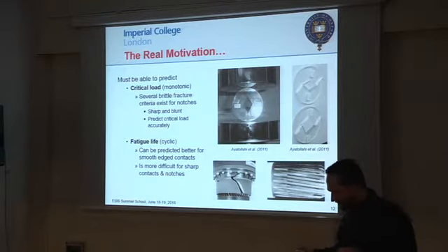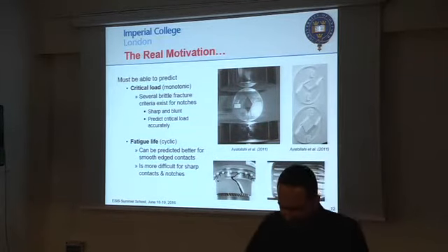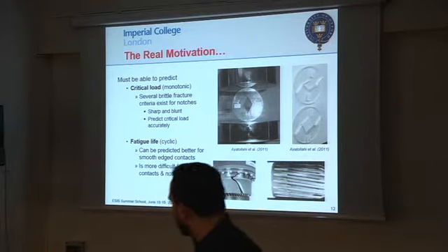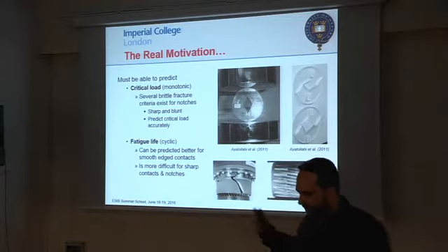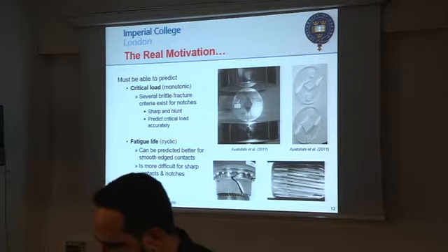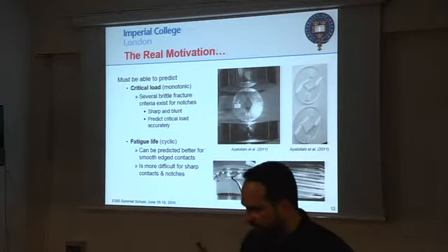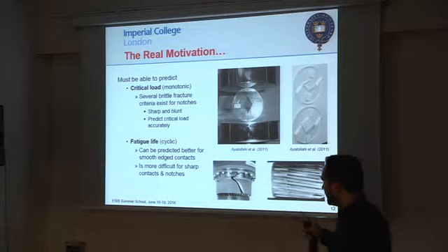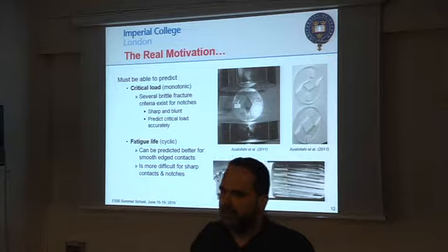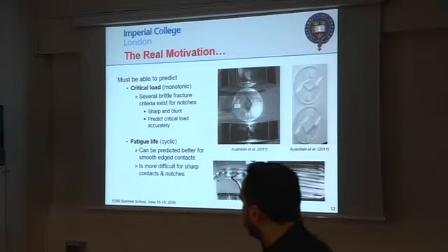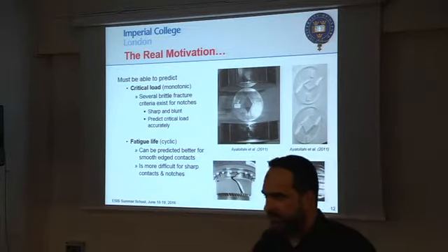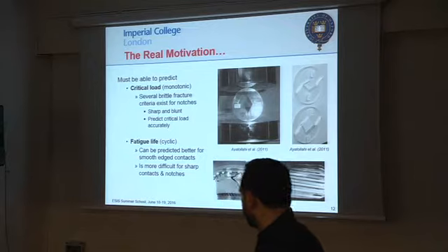But I was also interested in fatigue, because most of the failures we saw in the engines when we were working on these things were cyclic. So you actually need to go on for millions of cycles before you start seeing failures. So my research was really to understand both types of things, brittle fracture from notched samples, but also trying to predict cyclic fatigue in some of these components. And it turns out that you can use these methods in different ways to study these two problems.